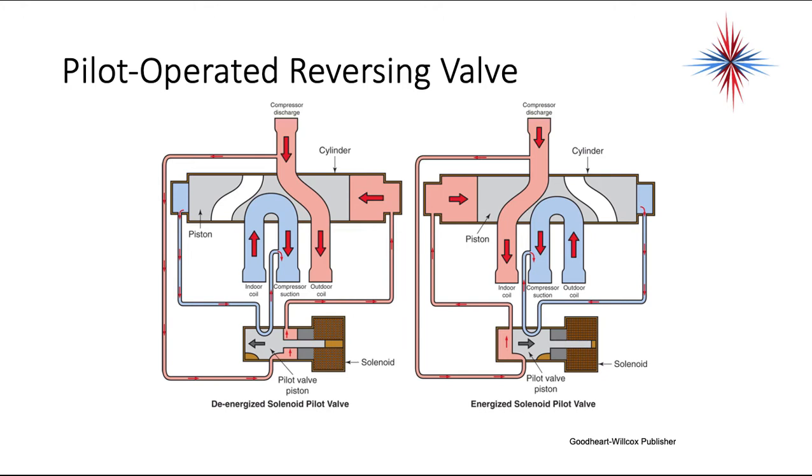Most often, it's going to be an O or a B terminal. If it's a B terminal, most often it's energized for the heating mode. If it's an O terminal, most often it's energized for the cooling mode. We usually want systems to fail into heating mode.